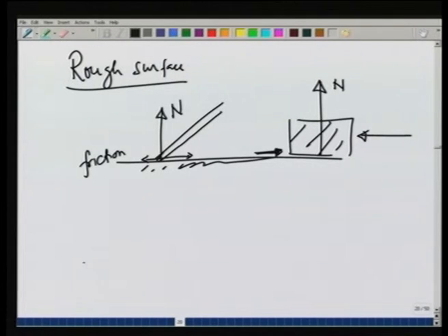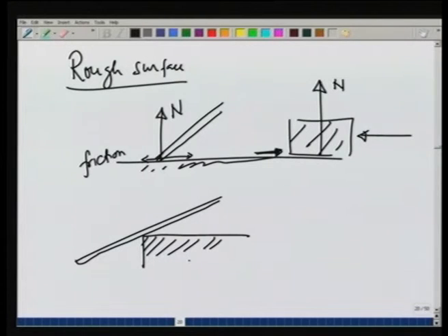By similar logic, if I have a plank or a rod on a smooth edge, then the force on this plank due to the edge is perpendicular to the surface of the plank. Of course, the direction on this side would not be there. The only direction in which the edge can apply a force onto the plank is in this direction.